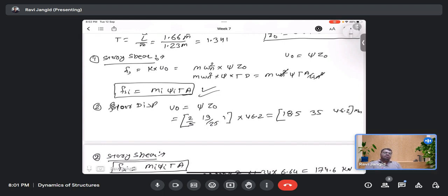No, I is given to you in the question. They have also asked you to consider whatever I is given. The external and inner diameter are used only to calculate the bending stress. Yes, you have to use the given 174. If I is given to you, then you have to use this.